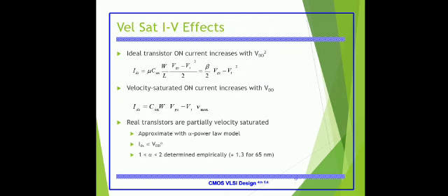And this is the velocity saturation IV characteristic. Under a strong lateral electric field, which is produced by the VDS, the charge carriers are accelerated, and the collisions between the charge carriers and the silicon lattice also increase. So beyond a certain level of this electric field, the carrier drift velocity saturates at a point we call VSAT, or velocity saturation.